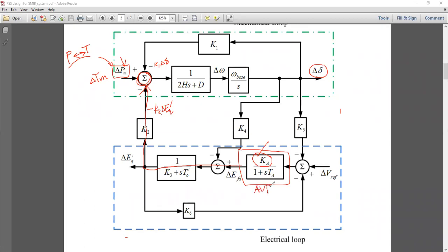Whenever the system was third order, there was no such problem for the parameters taken under consideration. But once we introduce this and start to increase Ka, the impact of this torque was such that it changed a stable system into an unstable one.